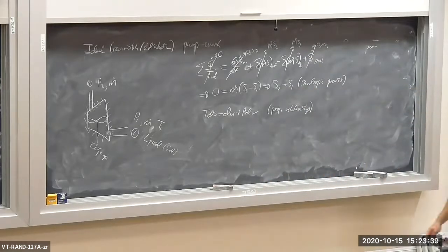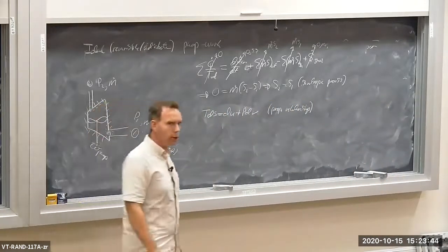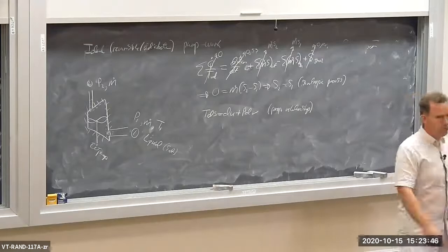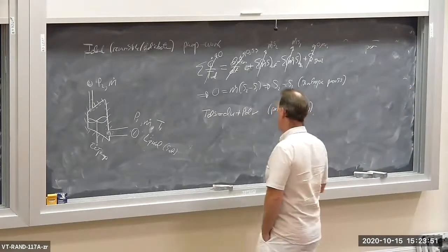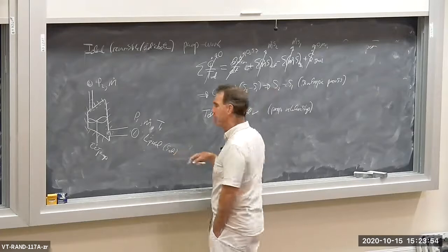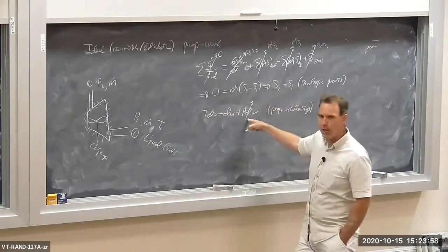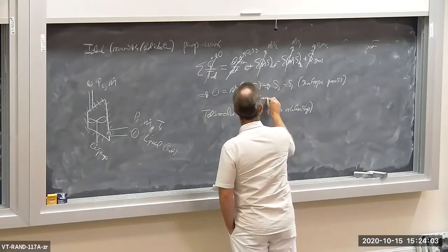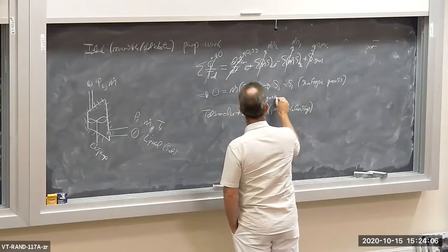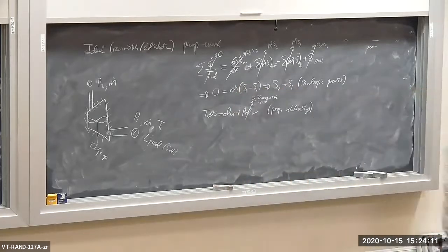Now, if we have a liquid, is a liquid compressible? In theory, no. I suppose you may be able to compress it just a little bit if you crank the pressure up by a huge amount. But the idea here is that a liquid is approximately incompressible. So for an incompressible, the differential change in specific volume is 0. Saturated or otherwise, a liquid is approximately incompressible. So the dV term is 0.